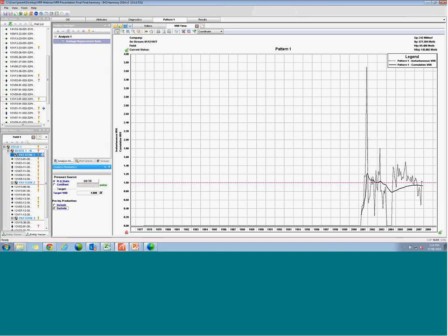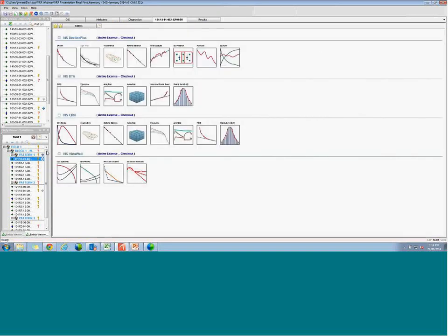Under pressure source, you'll see options for initial pressure and static pressure. You can have your source be constant. What I'm going to do now is add in some static pressure data to show that there is a difference between having it be constant or adding the static pressure data. If we think back to the formula that I showed earlier, the static pressure data is going to have different values for the different formation volume factors, which in turn changes what the total output from the VRR calculation is. So to add pressure data, I'm just going to launch one of the wells here.